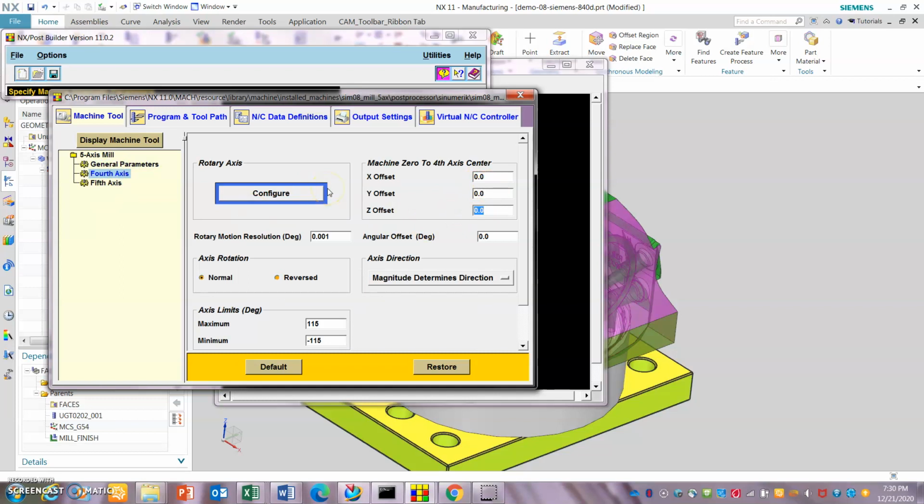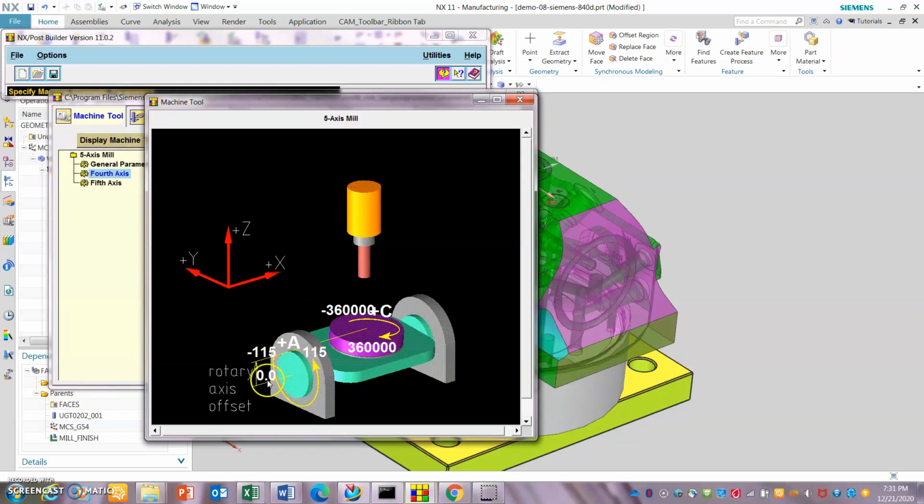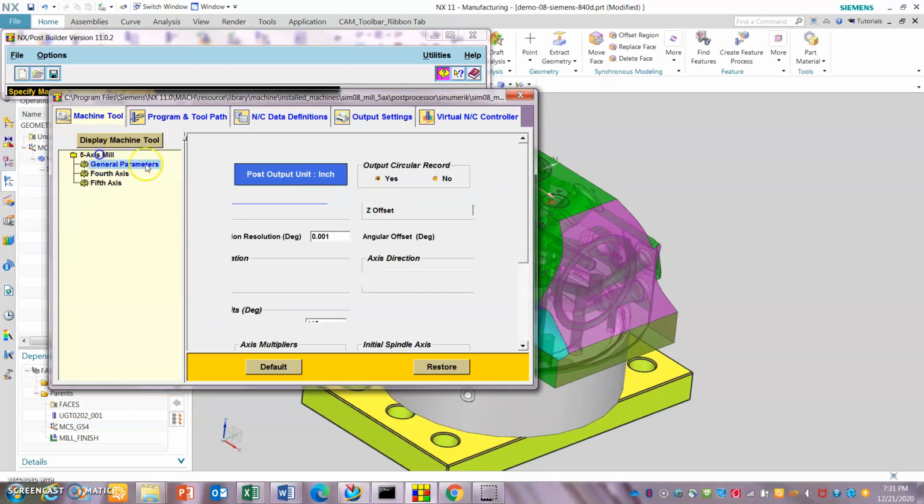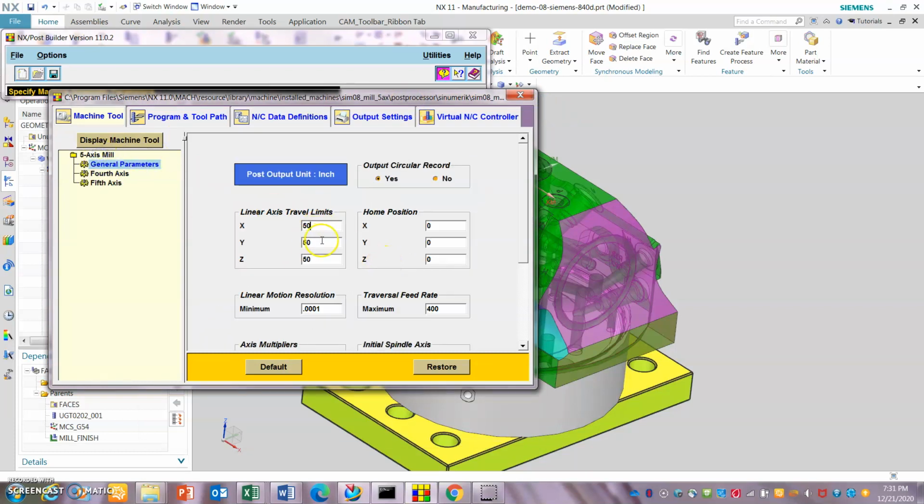So one of the most common controls is Haas. If it's inches, you go and put in the offset for a VF2. That's one of the common controls. But again, it depends on the offset: what you got from the top of the C table to the center line of the A-axis tilt, the intersecting point. So nowadays with RTCP, you don't need all those things. So it's zero.